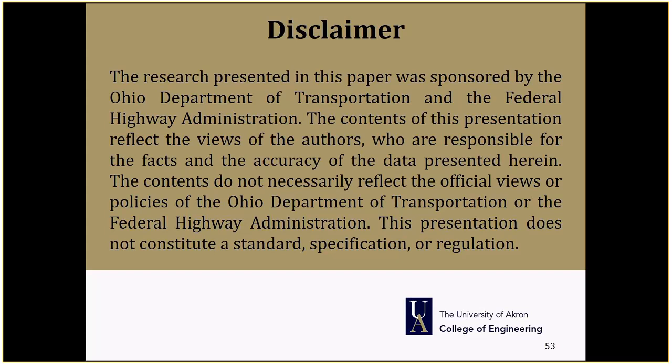Something else that we've noticed is that at times when our contractor is going to pave on top of these membranes, the membranes move a lot during the paving operation. And at the time, I never thought to ask just how much cure they gave before they got on it. You know, make sure the tack coat was appropriately cured.